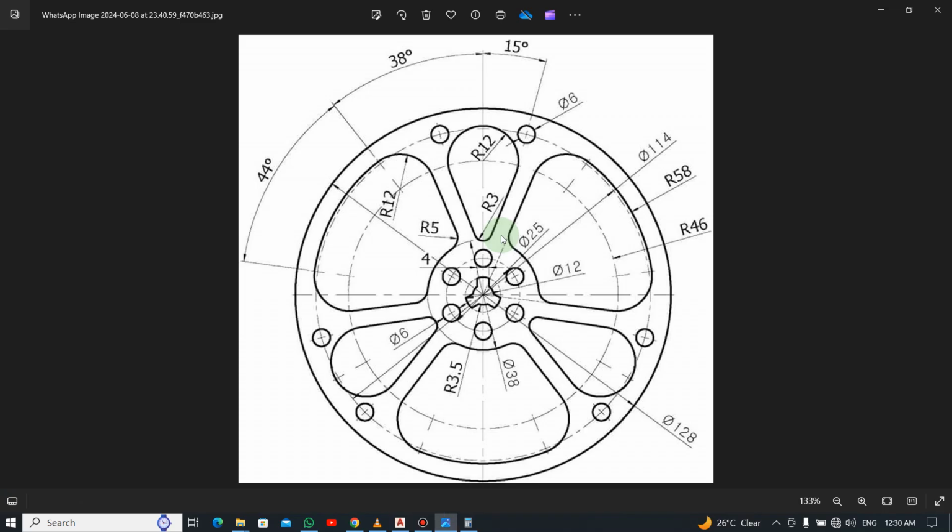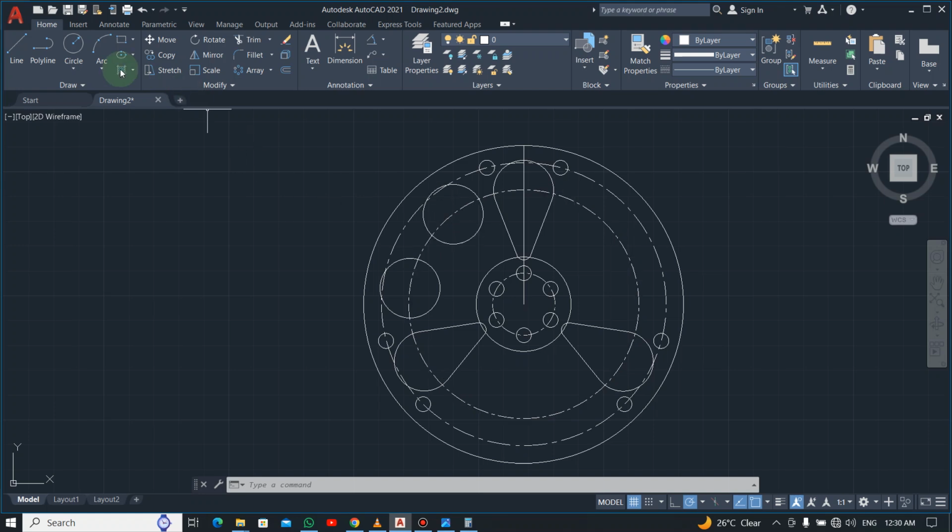So now let's try and get this line. Okay, so to get it, just line. When you come here, you pattern. That green circle thing over there is the tangent symbol. So if you see it, you leave it. But if you don't see it, you press on the shift and then you right click to select the tangent. So for example, now I'm not seeing anything. So if I select line to this circle, I'm not seeing anything. I'm just seeing the quadrant symbol.